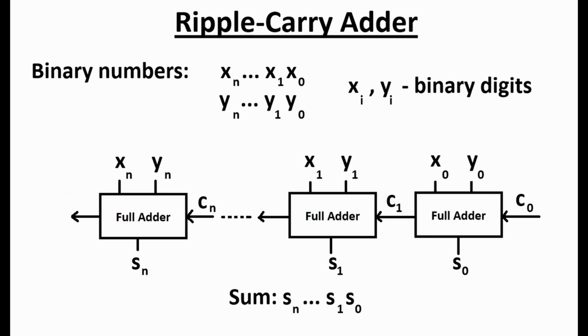This particular adder is actually not very efficient, since each stage has a processing delay that has to wait for the prior stage to complete, making it relatively slow. There are other implementations, like the fast adder. However, there also tends to be a trade-off in complexity and cost of these circuits for the added performance benefit.